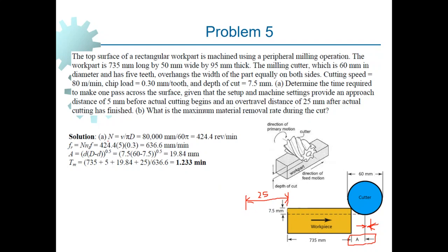First, we do the computation of the spindle speed in order to be able to compute feed rate later on. Because we know the cutting speed and the diameter of the cutting tool, we can easily work out spindle speed for this operation, which is this much.